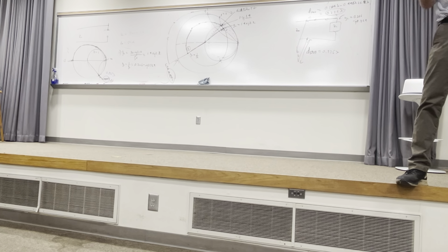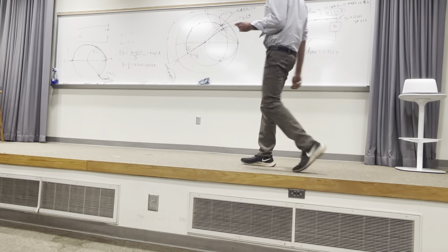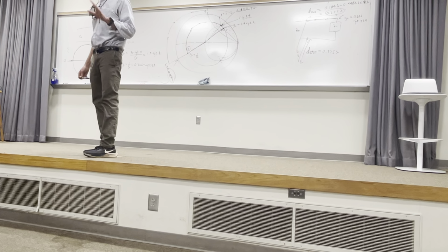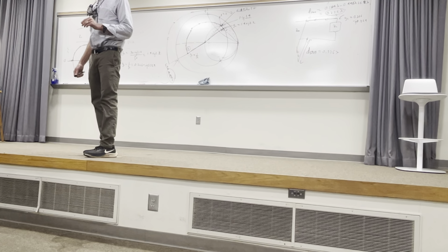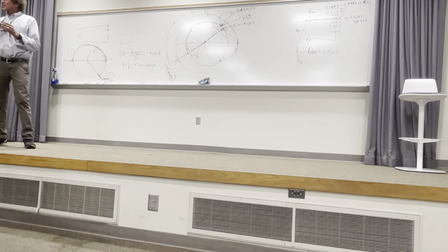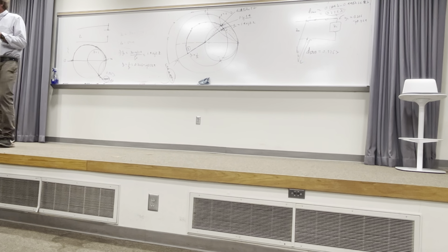We're definitely off. You're going to get that kind of variation. It's inevitable, you cannot avoid it. You're always going to get some variation. Now, the tool I send you will give you an exact value, but I'm going to level with you about one thing, and this is so important. Nothing that is fabricated is exactly what it says it is. There's imperfections in the dielectric constant, in the line material used, and the whole idea is this. You try to minimize the amount of slop and error, but no matter what you do, you can't.